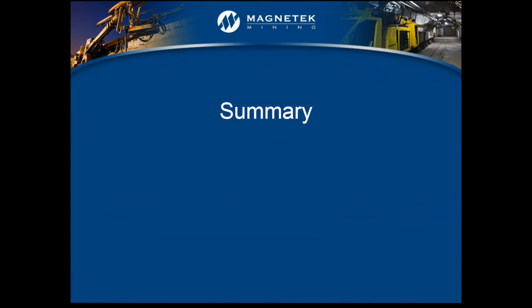We looked at traction of converting from a DC control to AC control on a battery-powered machine, and 1,000-volt drives that are becoming more common in underground mining applications. Lastly, we touched on benefits of integrating drives into control systems for better diagnostics, better feedback, and better safety for the operators.